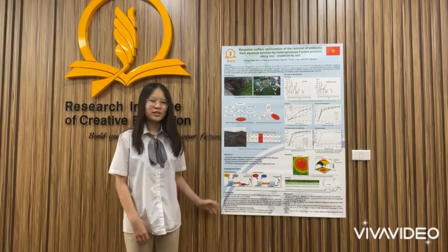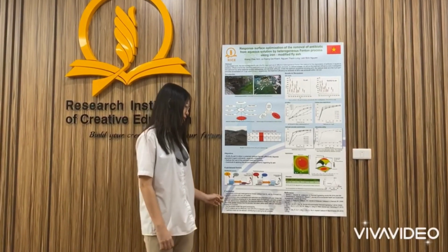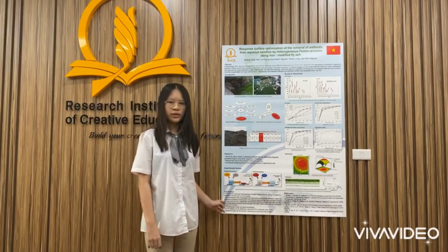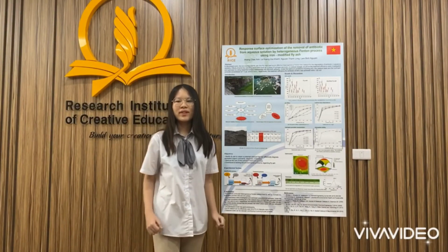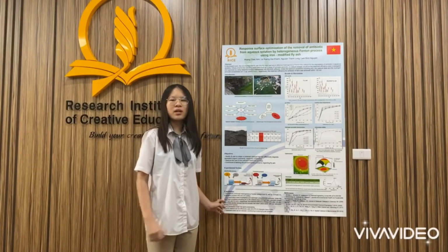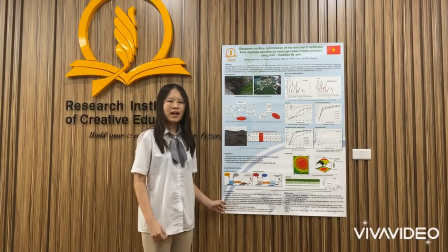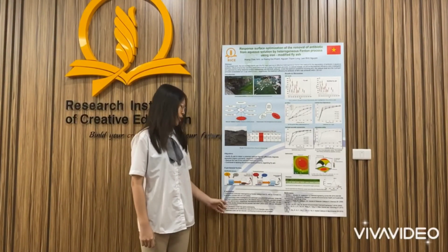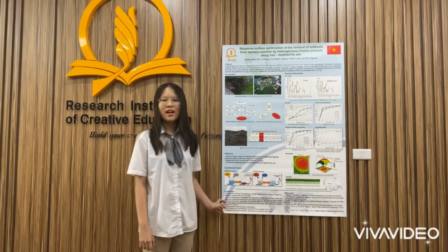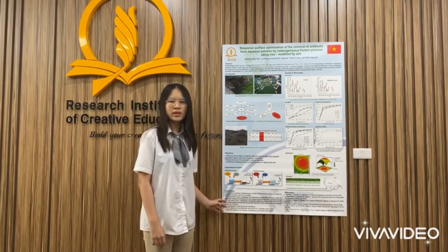So, as conclusions, we have successfully produced a heterogeneous Fenton catalyst from fly ash by a simple impregnation with an iron-containing solution. Key parameters were investigated and optimized using MODDE software. Under the optimized condition, including pH 3, the catalyst dose and hydrogen peroxide content of 1.2 grams per liter and 0.5 milliliter per liter, the treatment efficiency was about 95% after 120 minutes.